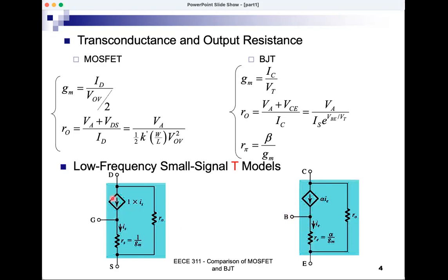While here, in the case of the MOSFET, this current minus this current would be exactly 0, because there's no IG. Even though there's a wire here, there's no current flowing there. So this current is exactly equal to this current, to make IG 0. While here in the BJT, this current minus this current, there is something, and this something would be the base current of the BJT.